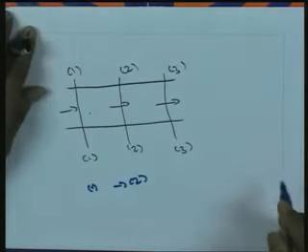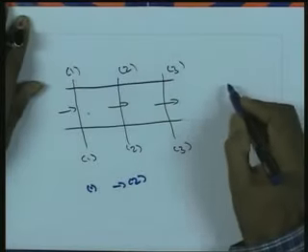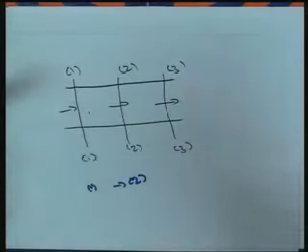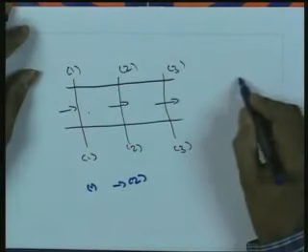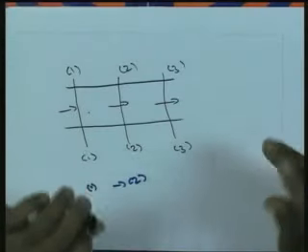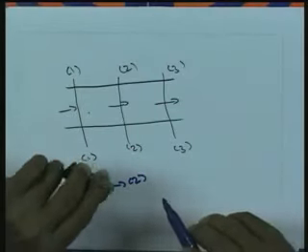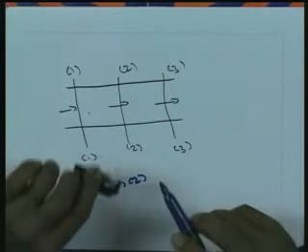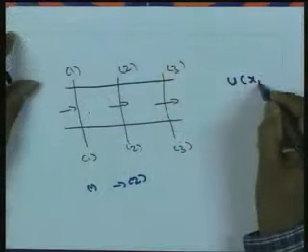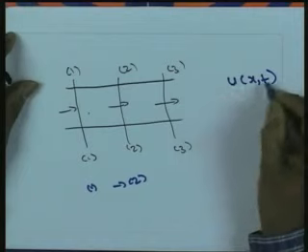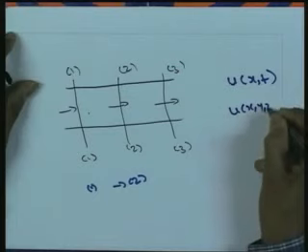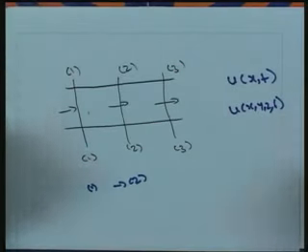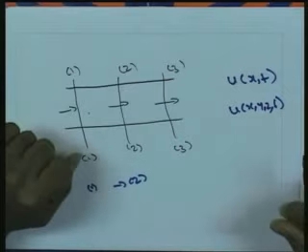As far as the third category, steady flow, is concerned, if the flow parameters are not changing with respect to time, that means only the spatial variation is there, then we say that the flow is steady. That means with respect to time there is no change in the particular fluid flow. And whenever the velocity is changing with respect to time, say in one-dimensional flow with respect to space and time, or with respect to x, y, z and time, then we say that it is unsteady flow, or we call it a transient flow.